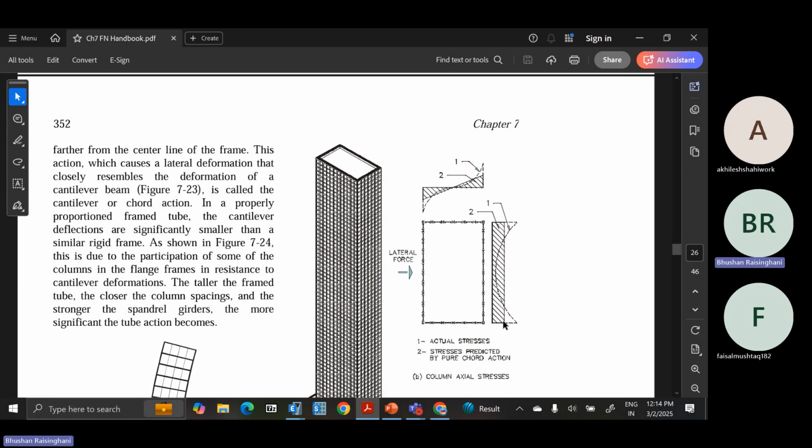To avoid this, we also have elevation bracings on the building. In many buildings that you see, the diagrid system is there. So cross bracing on the facade of the building is visible, on all sides of the building, along many stories, like 3-story bracing. Cross bracings or single direction bracings are provided. This is done to reduce the axial stresses on the columns. The tube-in-tube system for high-rise buildings also works the same way.